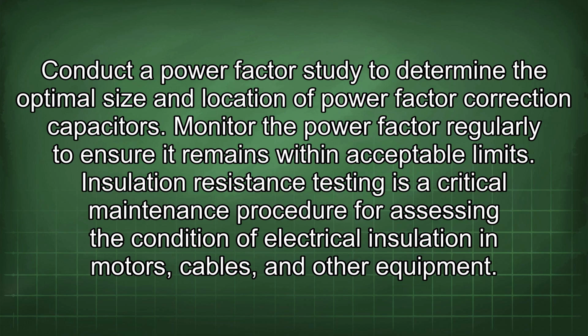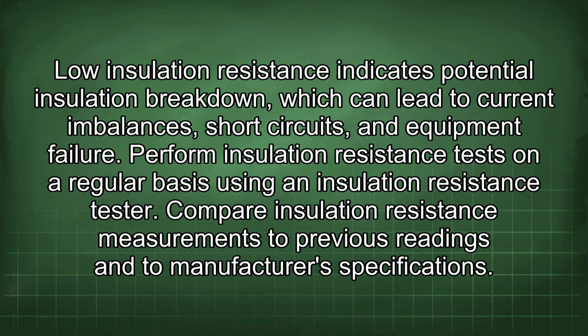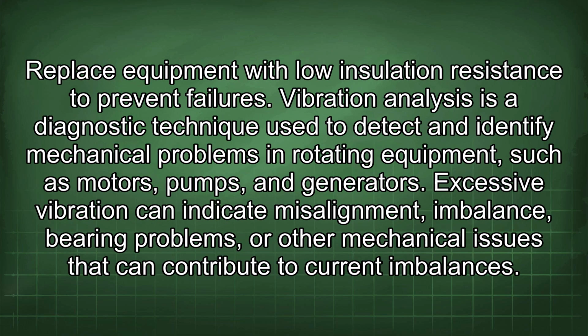Insulation resistance testing is a critical maintenance procedure for assessing the condition of electrical insulation in motors, cables, and other equipment. Lower insulation resistance indicates potential insulation breakdown, which can lead to current imbalances, short circuits, and equipment failure. Perform insulation resistance tests on a regular basis using an insulation resistance tester. Compare insulation resistance measurements to previous readings and to manufacturer's specifications. Replace equipment with low insulation resistance to prevent failures.